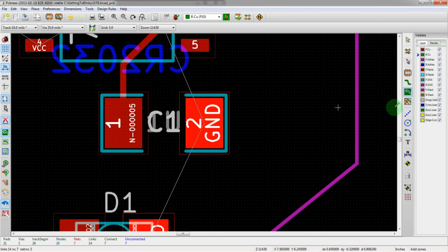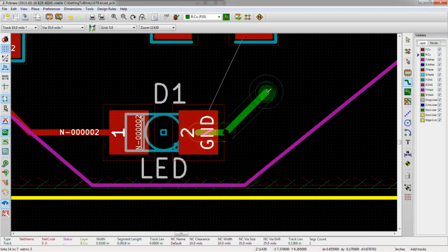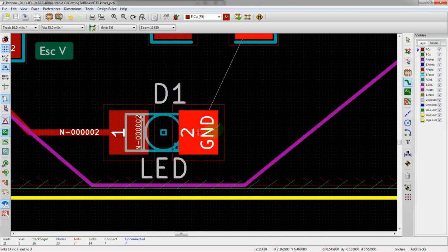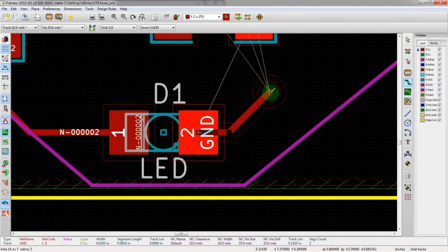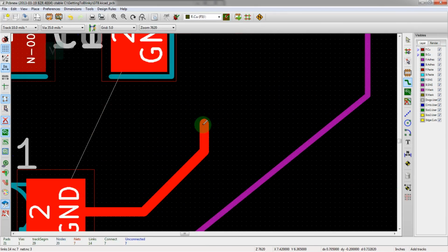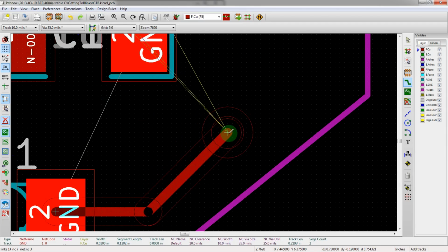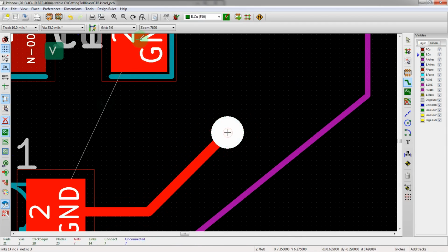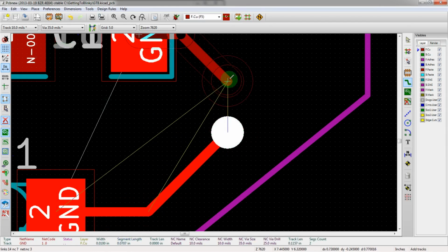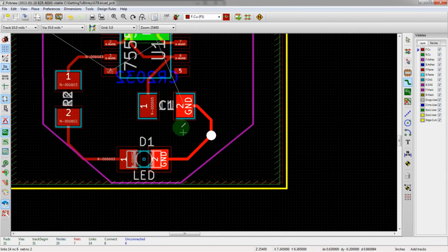Turn the copper layer back on. We want to draw a via. These two can share a via, actually, which is nice. Oh, wrong layer. We can drop a via here. Oh, shoot. Let's undo that. Draw V, double click, and then from here we can connect to the same. Double click. All right, and these two are now connected to the ground layer.